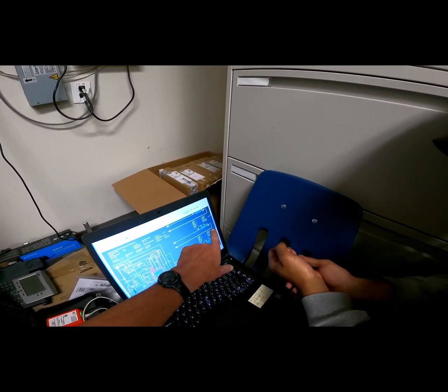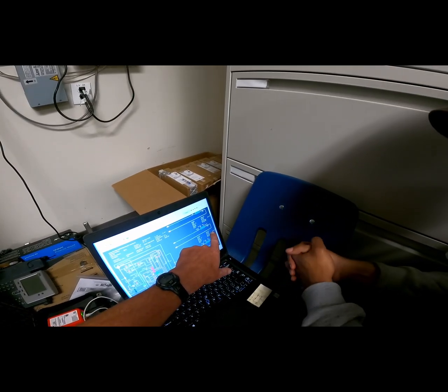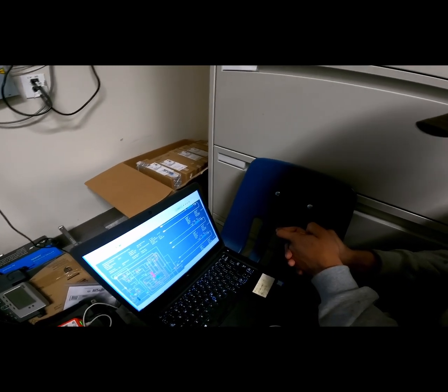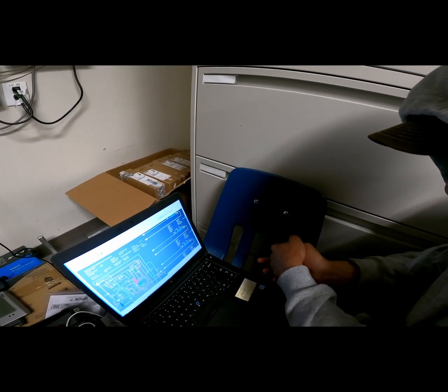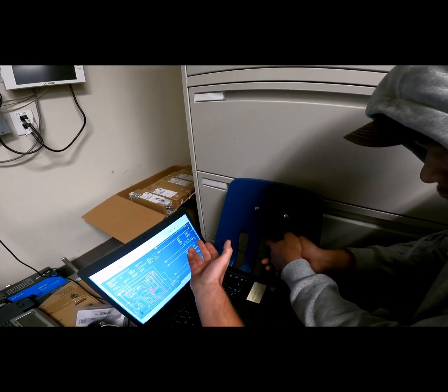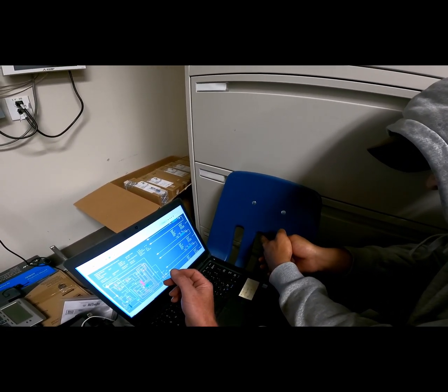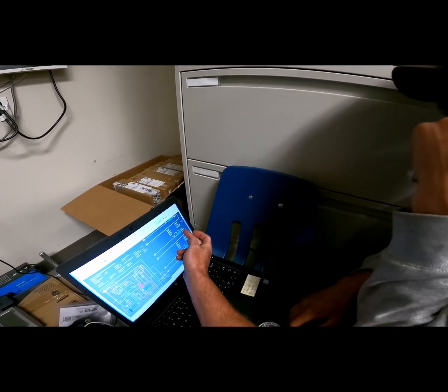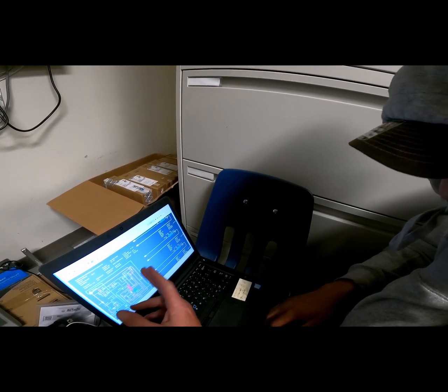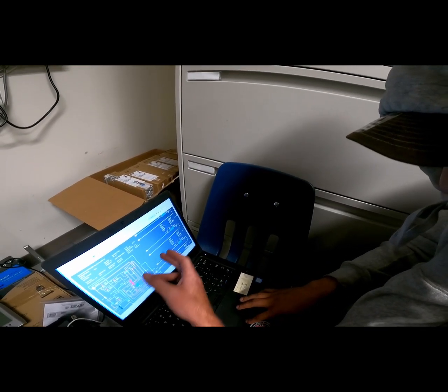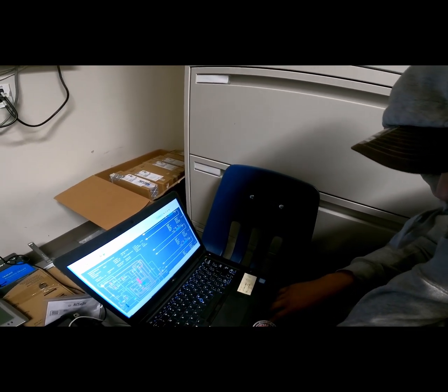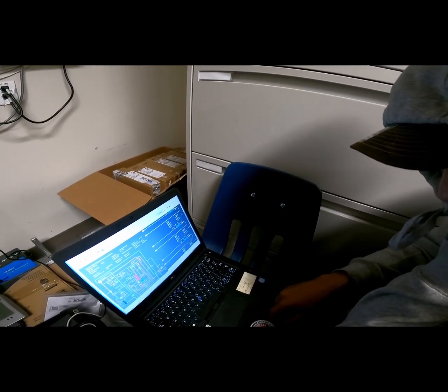That's an LEV. It's just an electronic expansion valve, but it's at 249 pulses. I believe that 480 is wide open and 41 is fully closed. And so it's about midway right now. And it's metering that refrigerant in, and the second that it becomes an aerosol refrigerant, it's 47 degrees. That's between 35 and 50, so that's good. By the time it goes through there and evaporates, it's gained, what, 3 degrees of superheat? Mm-hmm. So that one's working properly.